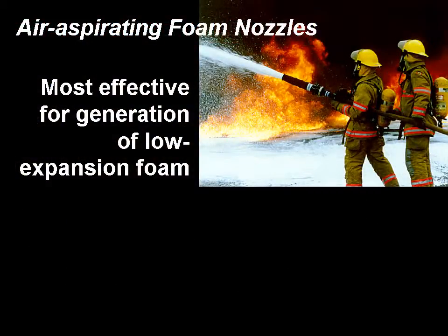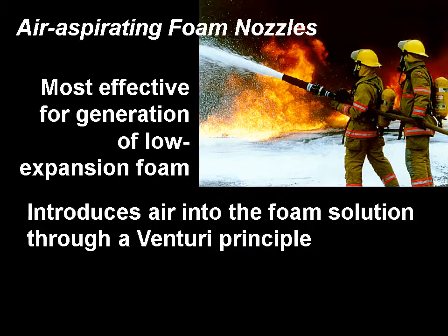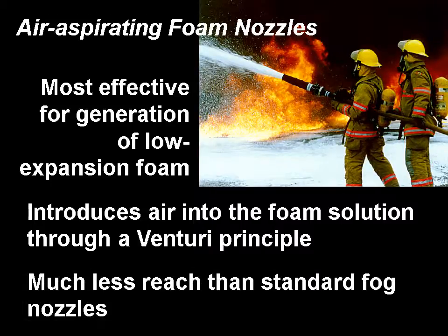Air aspirating foam nozzles are most effective for generating low expansion foam. They introduce air into the foam solution through a Venturi principle. Much less reach than standard fog nozzles. Provides maximum expansion of the foam. Some manufacturers have aeration attachments for fog nozzles.